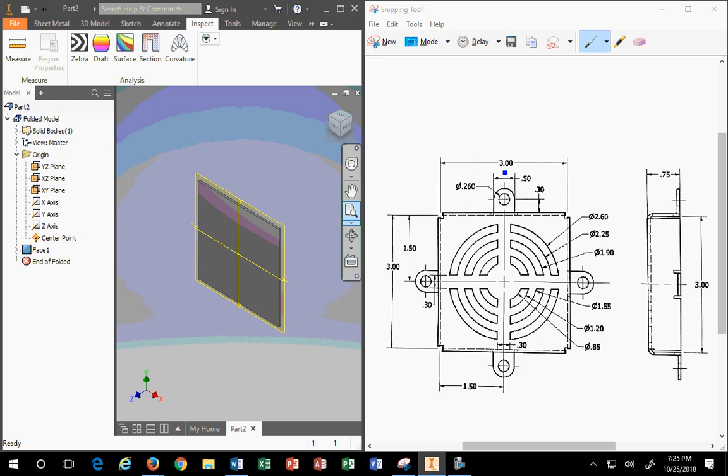So when we look at 3, and now we understand that 3 is to this interior space, what is it to the exterior? I know, I can't draw a straight line worth a darn. 3 and what? 3 and 1/8. Because it's that inside plus material thickness, right?